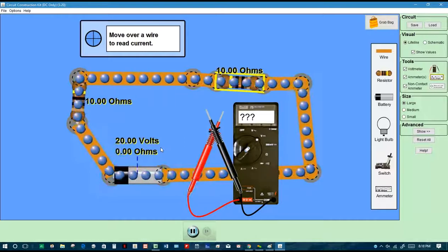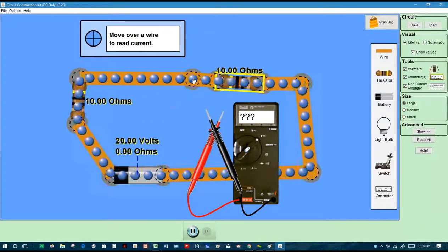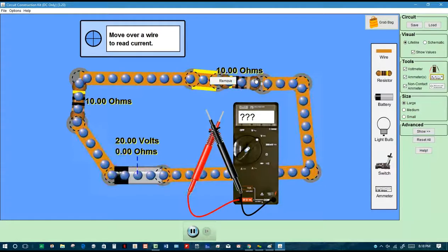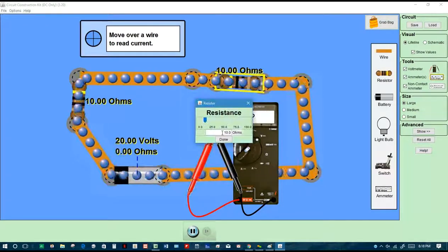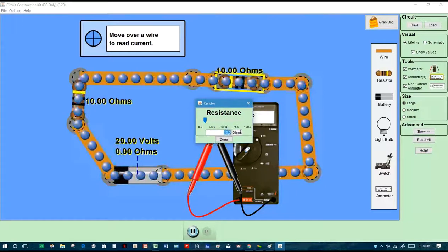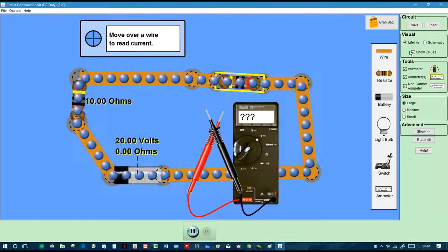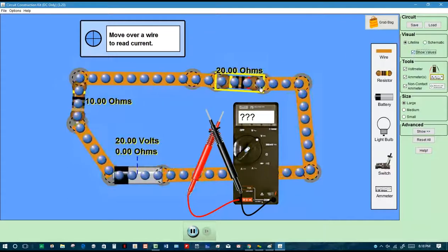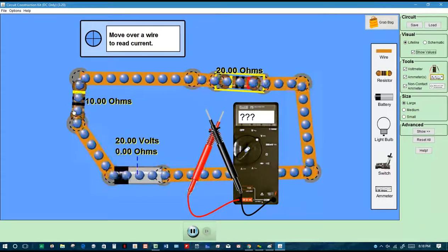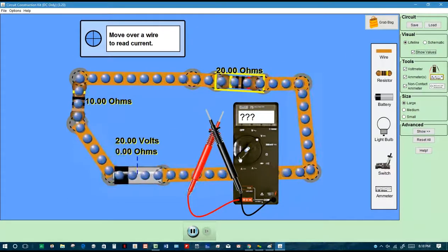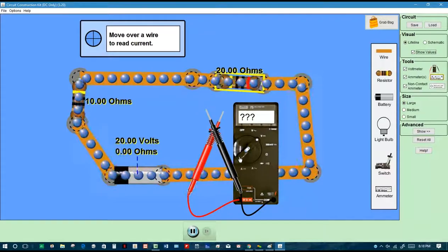And so it uses equal amounts, 10 volts, to get through each because it's the same difficulty to get through both, right? Yeah. What if this was now a 20 ohm resistor, though, and the other one stays a 10 ohm resistor? Will the voltage drop still be 10 and 10? This is now a 20 ohm resistor that I've put here on the top, and a 10 ohm resistor on the left. When I go measure those voltage drops, will it still be 10 and 10?